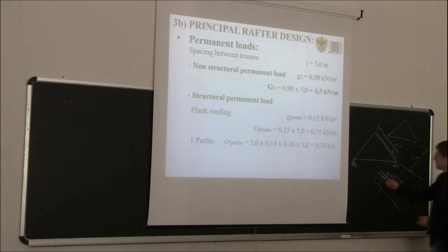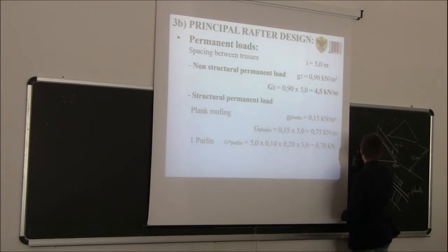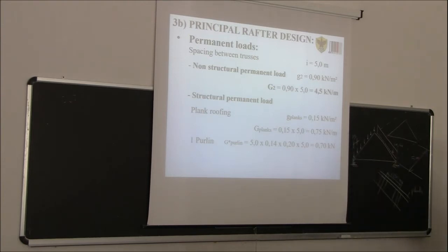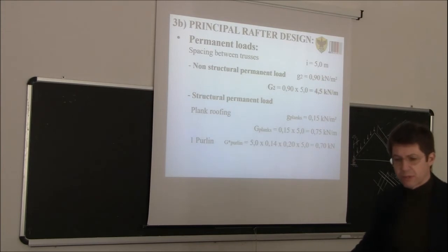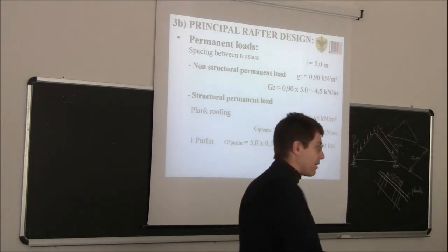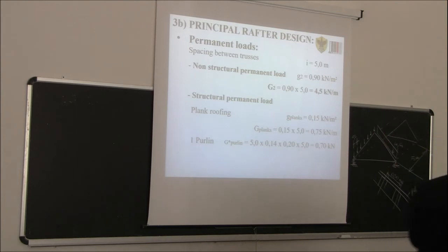So in the end, the actual scheme would be something like this, where this distance here is 0.5 meters. Okay? So strictly speaking, what we should solve is this system here, with some point loads. Now, if you remember, we also mentioned this 2 years ago, 1 year ago. If you have a beam with several point loads, you can also, by making a very little approximation, transform those point loads into an equivalent uniformly distributed load.